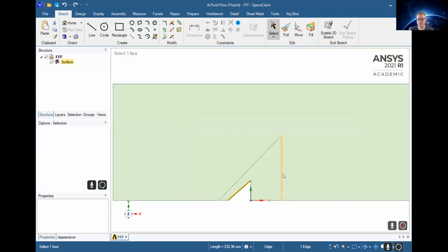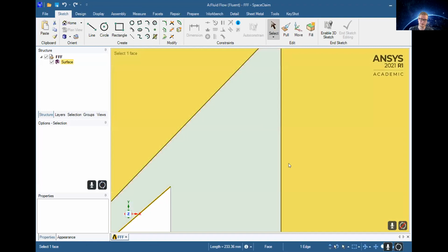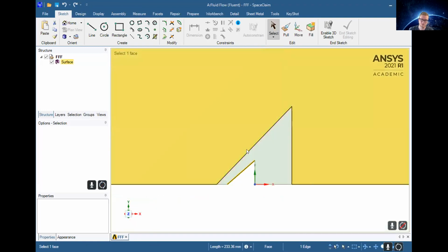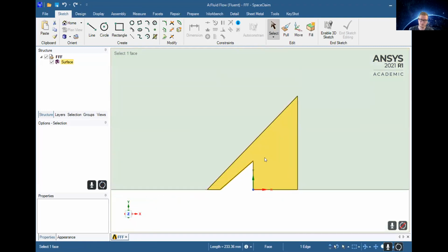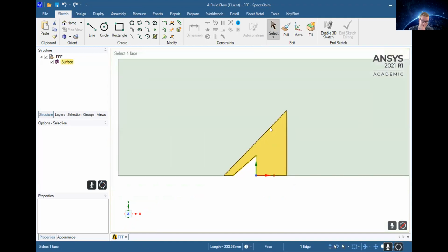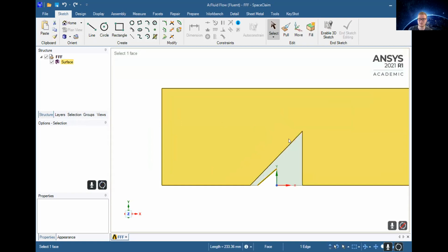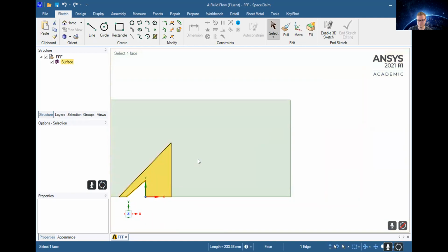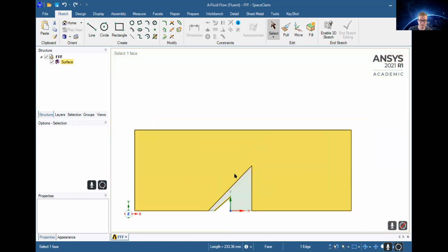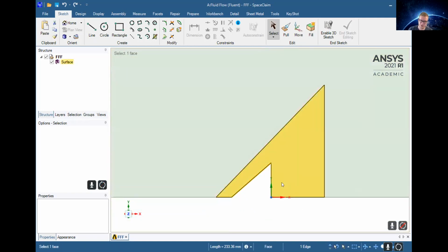but with that length of 15 centimeters. I'd also recommend creating a smaller triangle here to do finer meshing. This will help make it a little bit more accurate, and we're going to refine that in the meshing process. And this is going to be our far field, and it's going to be a little bit less meshed, but still pretty finely meshed to about e to the -2 power. So next, let's go on to meshing. Definitely only do half of the triangle. It makes it way easier and way quicker, and you can do computation a little bit faster.